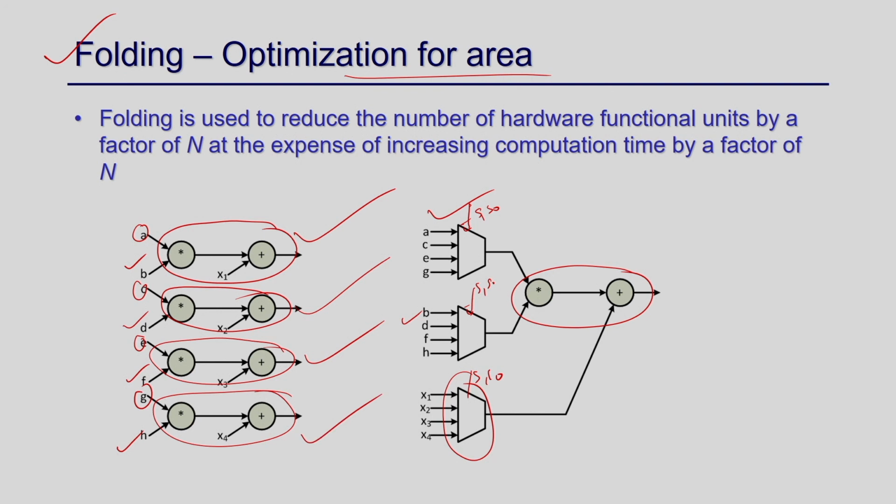So, basically what I am doing here is time division multiplexing. I am going to use 1 copy of the circuit, and I am going to multiplex the input, but it is a time division. One copy of the circuit cannot perform 4 operations at the same clock, so I have to distribute them over 4 clocks. Earlier this circuit was working in 1 clock, because they are all parallel. This will take 4 clocks, because time division multiplexing is happening here. Okay, I will come back to that.